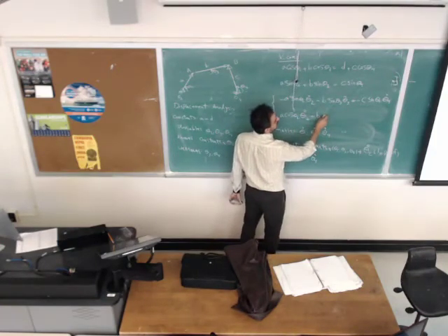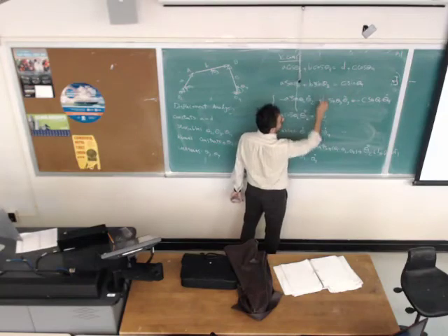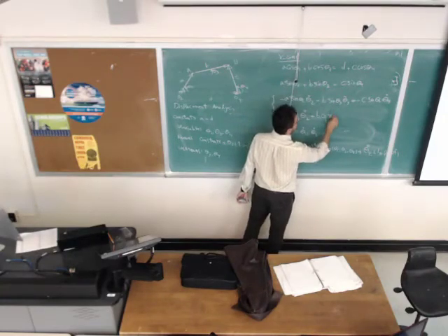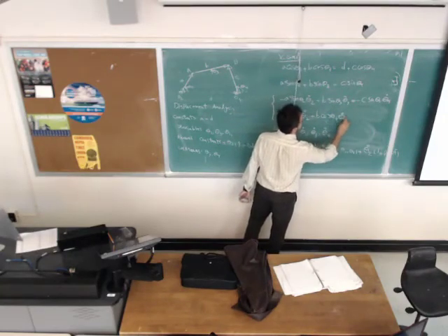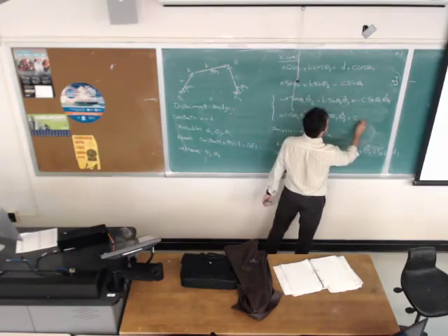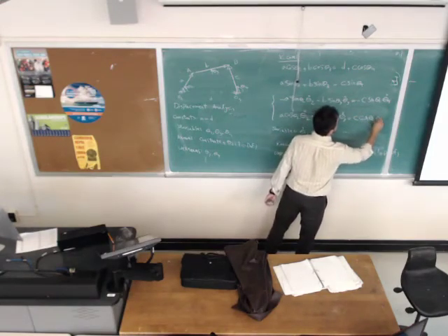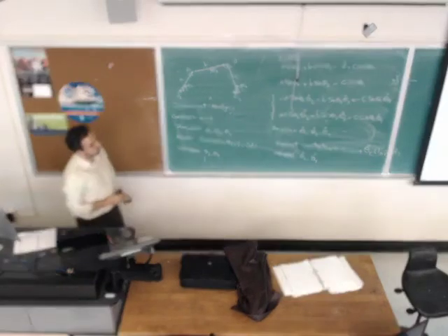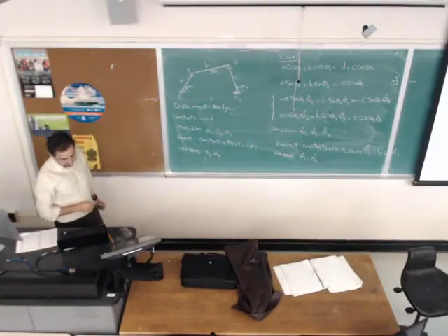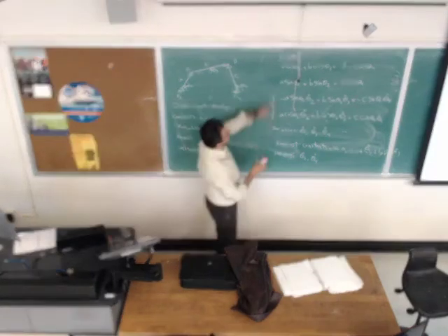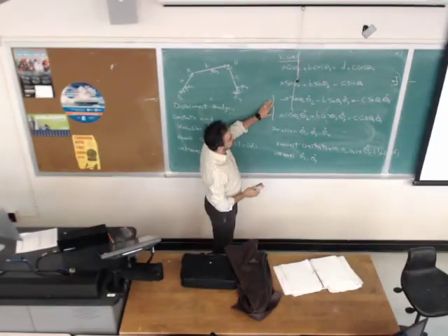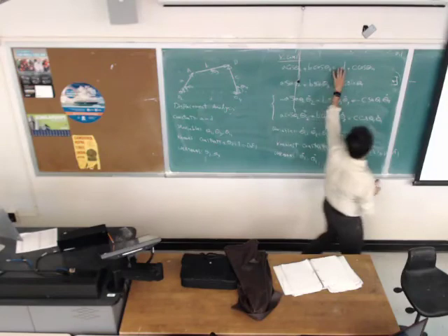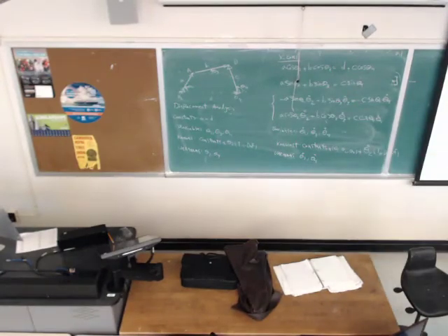We should use the chain rule: derivative of sine with respect to theta 3, which is cosine of theta 3, theta dot 3, equals c cosine of theta 4, theta dot 4. From the displacement equation, we could end up with the velocity equation.